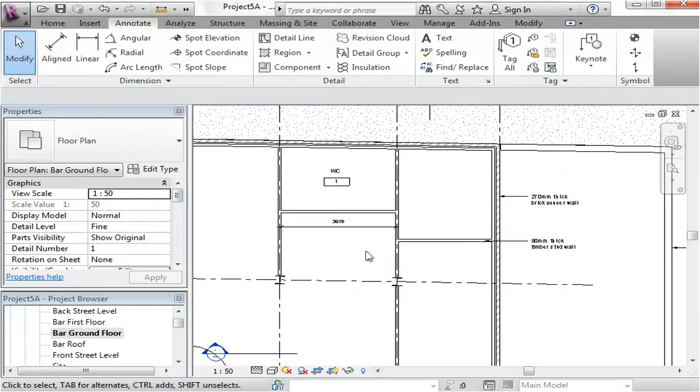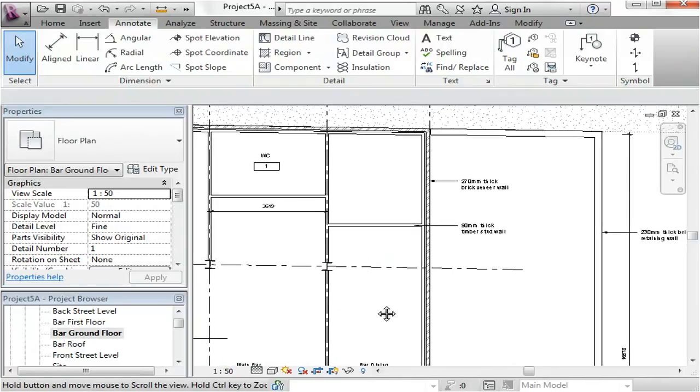For the moment though, you need to go back into all of your drawings, all your building design, sorry, and go into all your views and start dimensioning all of the views and adding notes to all of the views. Please keep in mind that you have to have your drawing at a particular scale, so you might want to change your scale now before it gets too late, and this will influence the annotation and dimensioning.